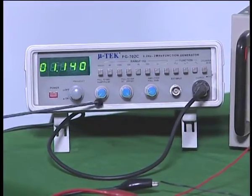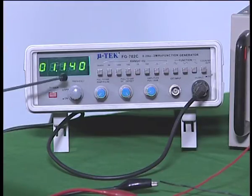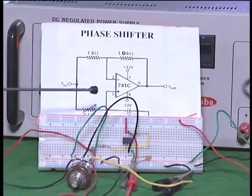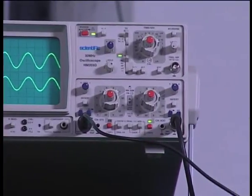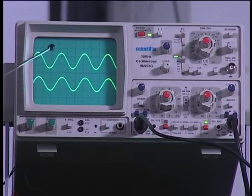I have chosen some 1 kilohertz as the frequency, 1.14 kilohertz, and the output is connected at the input of the amplifier here, and the output of the amplifier is monitored using an oscilloscope. The two traces that you see here are basically the input and the output both together. So, you can see they are actually in phase. When the input is going down, the output also is going down, they are in phase.